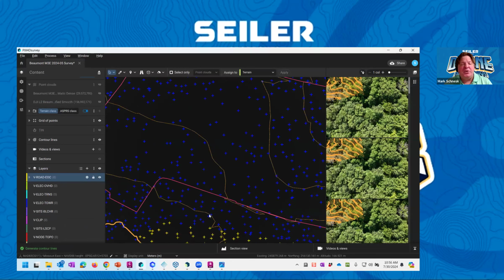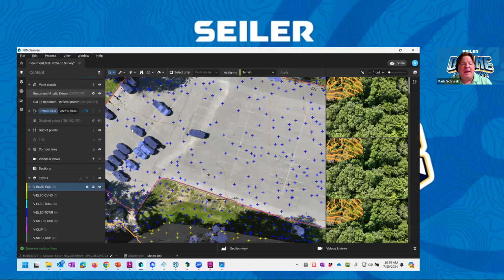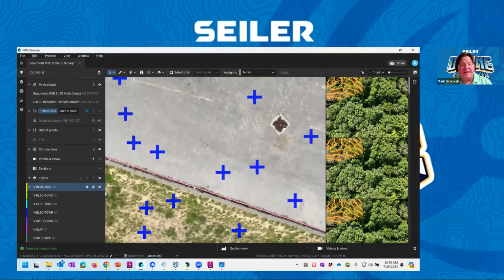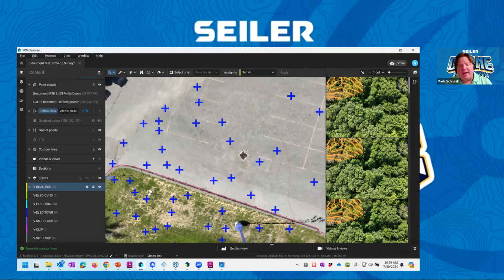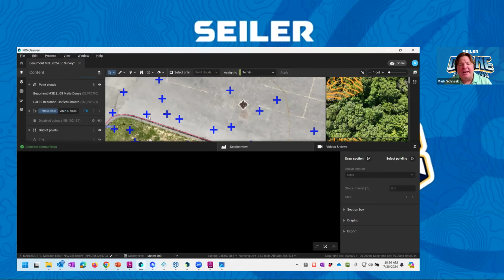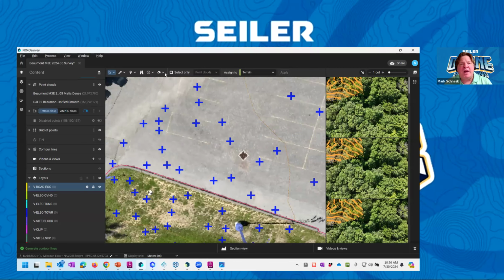So you're going to be using these views where you're going to be showing the point cloud, not showing the point cloud, showing the TIN, not showing the TIN, being able to see those lines, to be able to extract these and do cross sections as well. I have profile views available in either of these to help me. There are some semi-automated tools in here as well for extracting things like volumes or stockpiles, feature lines and catenaries, road marking, pavement marking, roofs and wall detections to create 3D lines, points, and planes.